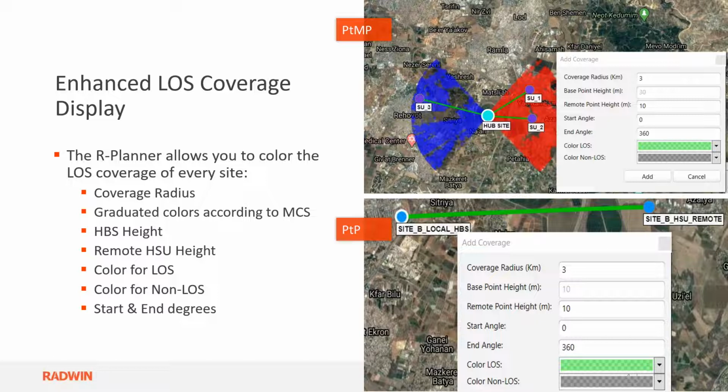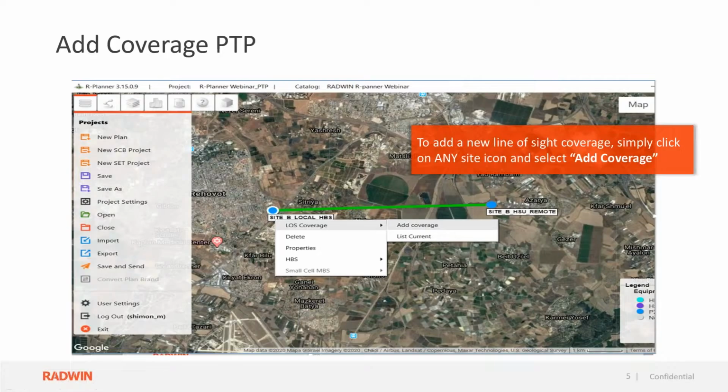It means that if I have coverage of 3 kilometers radius and I have too many subscribers, more than 64, maybe I need to add an additional sector. Maybe I need to use the dual carrier, the 5 and 5 on the same sector. And we can get more subscribers, more capacity and more throughput per a given sector.